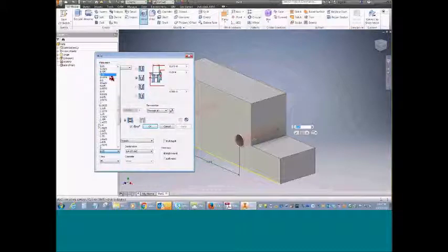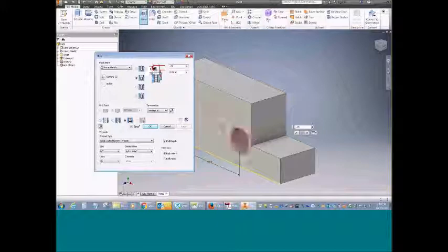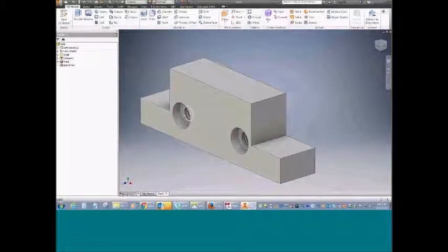So this is a half-inch thread, 1/2-13. We'll go right-handed, full thread depth, and then the counterbore. It's kind of a non-standard hole, and how deep does that go? 1/4 inch. All right, so we got our two holes in there, and there's some other features on this part.